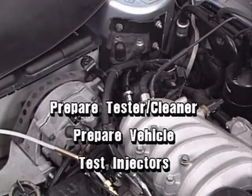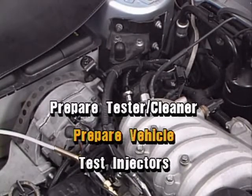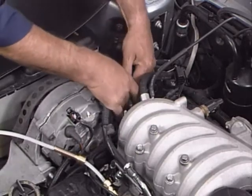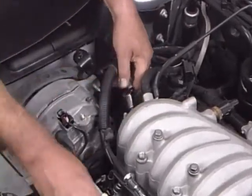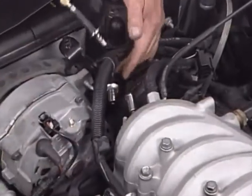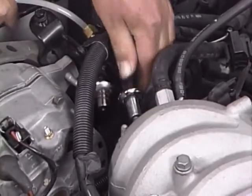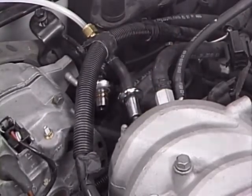The tester is ready now, so we'll prepare the vehicle. First, and very important, follow shop manual instructions and relieve the pressure from the fuel injection system. With pressure relieved, disconnect the fuel supply line in the vehicle and connect the fuel supply hose from the tester cleaner. The tester cleaner supplies fuel to the injectors during the test.